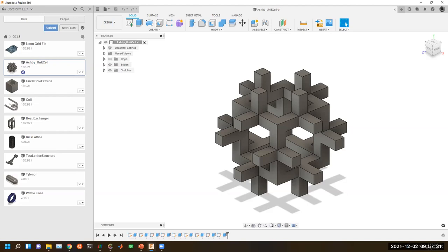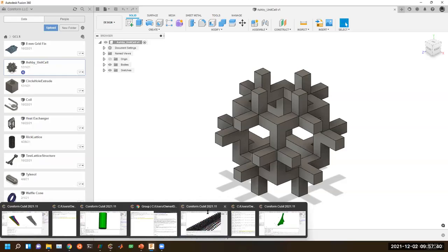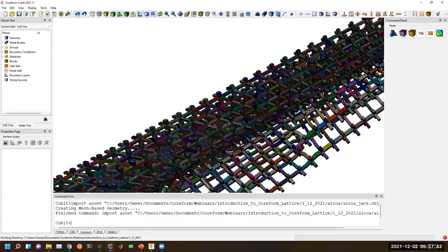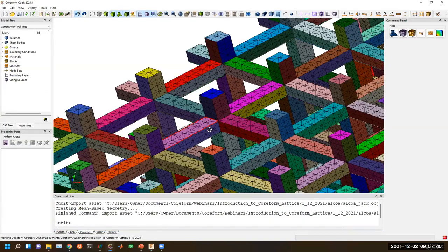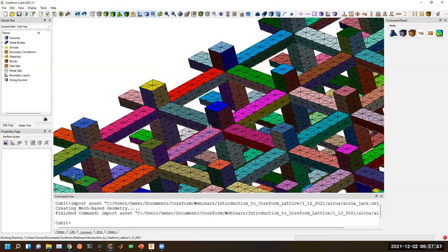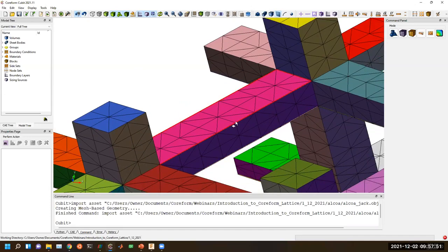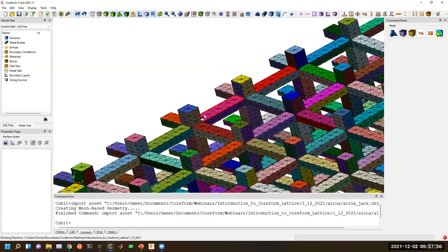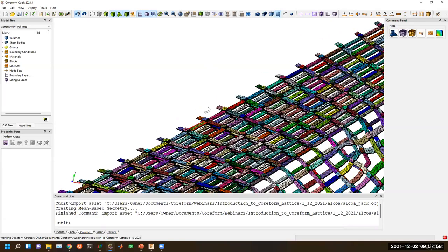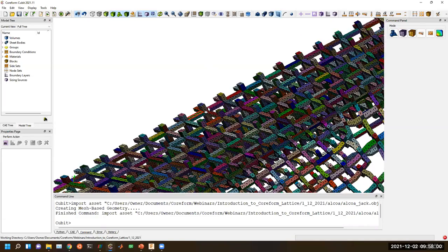Julia has asked whether or not we need to merge each single cell to another. What I'll say is that these, and maybe Mitch, if you want to chime in, they inherit the continuity of the underlying mesh. So even though it doesn't look like it, these cells are already merged together and united. We inherit the smoothness, which means there's already at least C0 continuity between the cells.